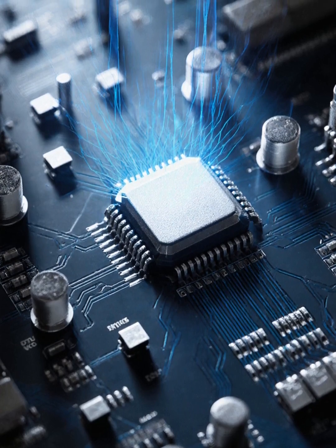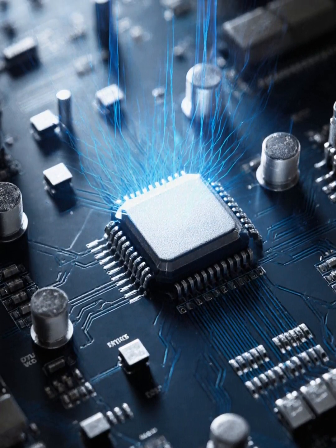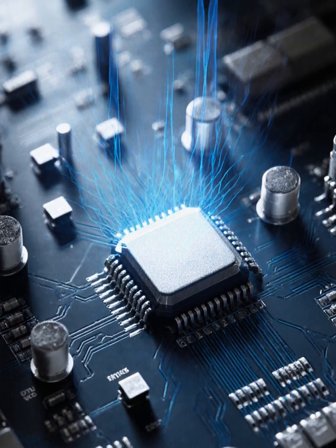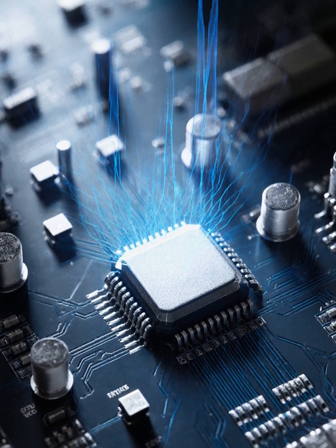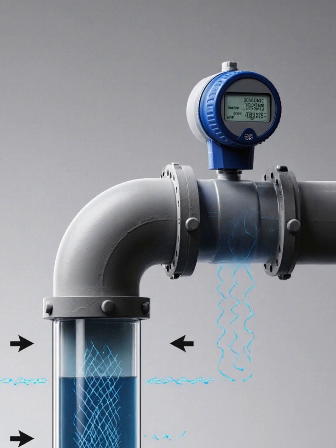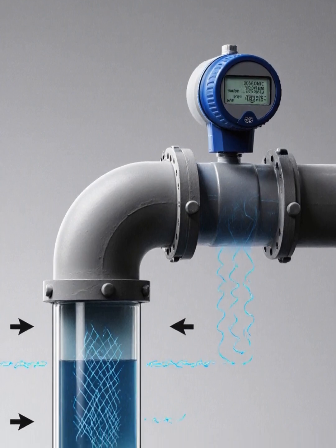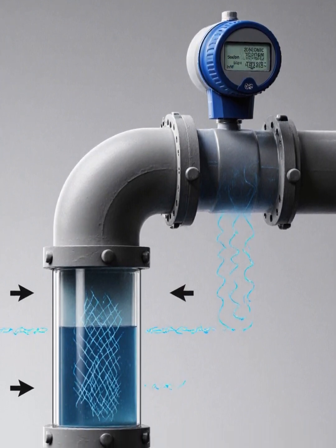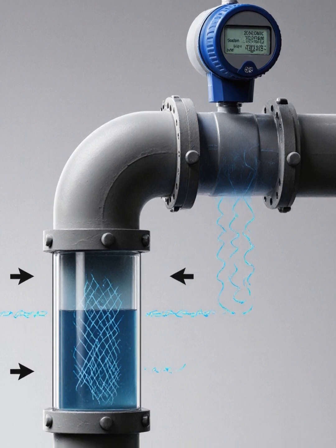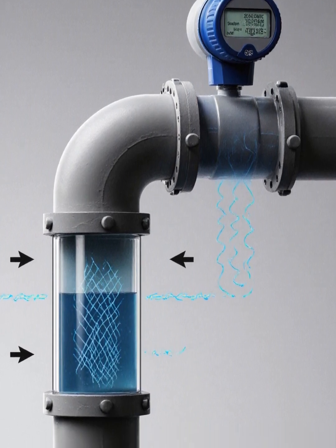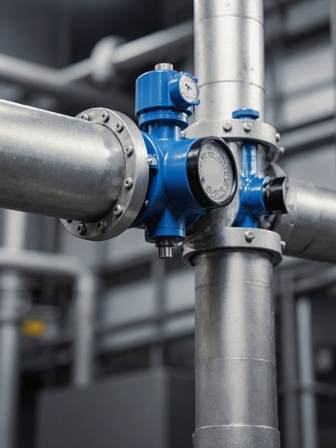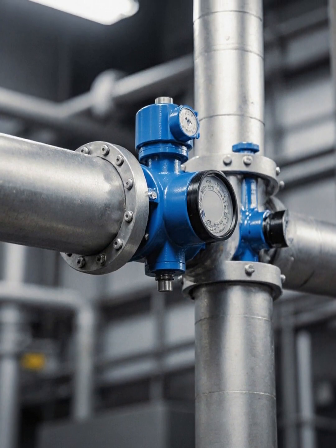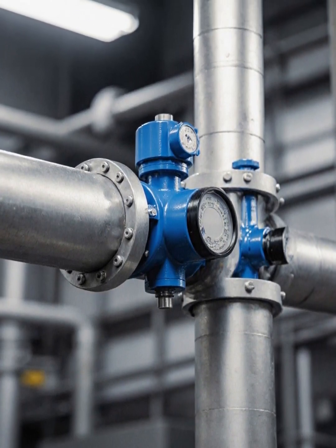The electromagnetic field coil assembly is excited by pulsed DC technique, which eliminates the interfering noise and provides automatic zero correction. 2. Ultrasonic flow meter. Working principle. Ultrasonic sound waves are sent through the fluid, and the time difference between upstream and downstream signals reveals flow velocity. The transit time flow meter utilizes two transducers that function as both ultrasonic transmitters and receivers.